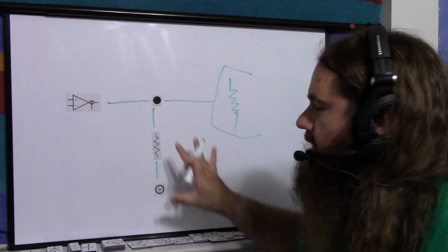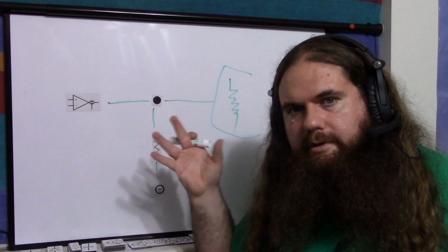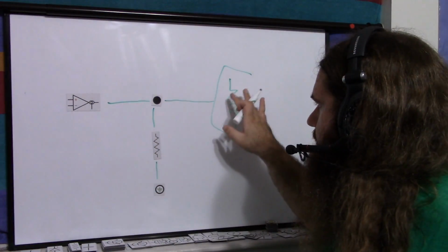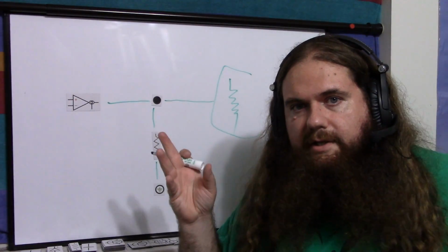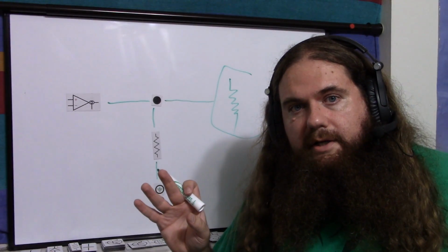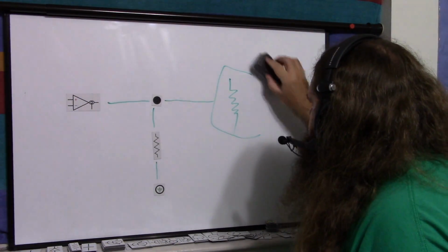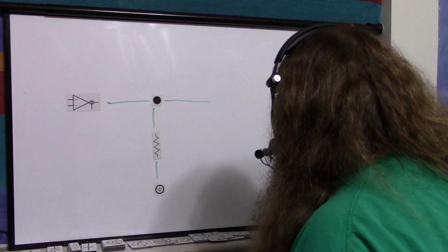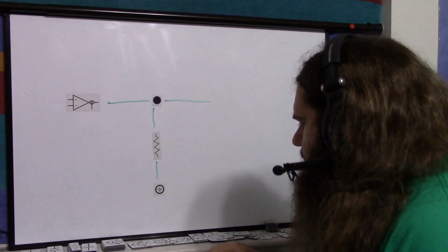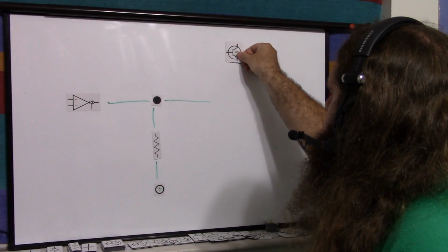It's going to try and put out the same current. So if your impedance is changing at all, whatever's reading this voltage, if that's changing at all, then your signal is going to get distorted. So what you do is you buffer it. There's a million different ways to buffer it, but this is the way Texas Instruments buffers it. It's called a voltage follower.